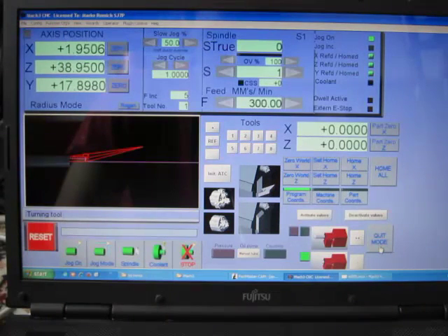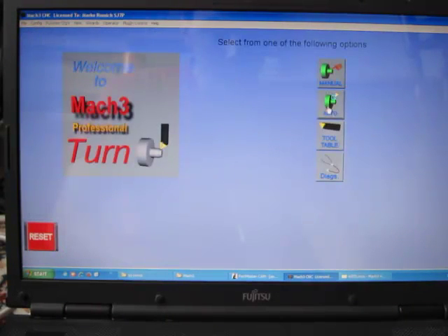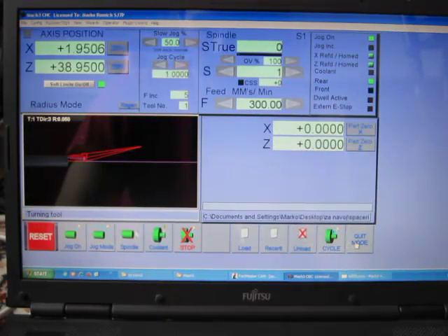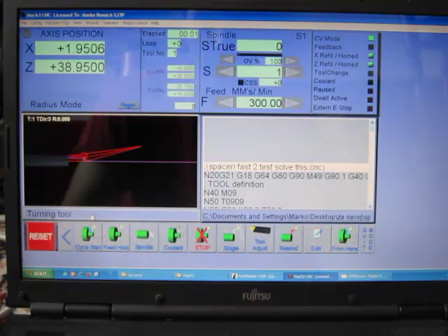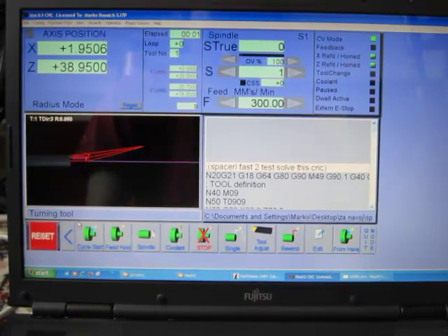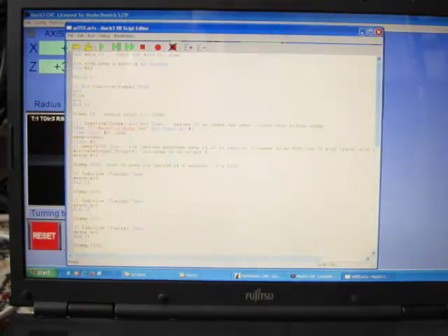And I concluded that when I go into auto mode, I think that Mach3 is prepared in such a way that all macros that are running are stopped, and because of that my macro M55, in which is the code for counting impulses and for control of lubrication, stopped working.